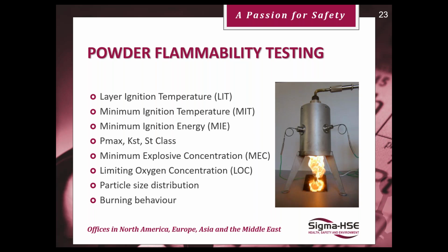If it requires 1,000 millijoules to ignite that dust-air mixture, the MIE of the powder, for example, or the vapor or the gas, and the energy source, say a person, could only generate 30 millijoules, which is a lot less than 1,000 millijoules, that means a spark discharge from a person has insufficient energy to kick off that combustion reaction.